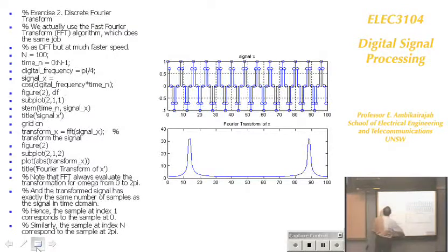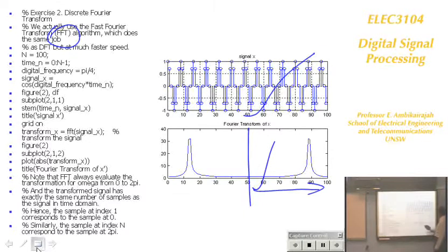So this is a typical example of a fast Fourier transform implementation of a signal, and here's your signal. You use the fast Fourier transform explained there, and these are the two frequencies you have got occurring here. This now becomes K. K is your frequency position, and now you can translate K into frequency. So if K is 5, then I will say 5 times delta F is my frequency. Delta F is my frequency resolution.